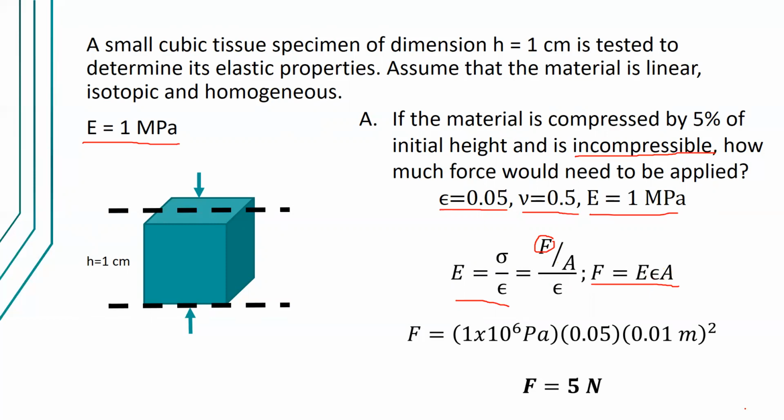Now, you have to substitute the given. So the modulus of elasticity is 1 megapascal. Strain is 5%. Area is 0.01 square meters. Okay, yung area ng isang face. 0.01 raised to 2 rather. And the force is 5 Newton.